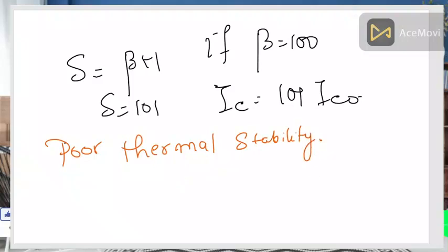This circuit is totally not good for proper amplification. Though it has some advantages, it is very simple and you require only one resistance. Calculations are simple. These are the two main advantages, but the disadvantage is that the stabilization is very poor, because you have no way to stop the automatic increase in the collector current due to temperature. Now suppose you change the transistor and beta changes, then IC will also increase by the same factor as the base current is